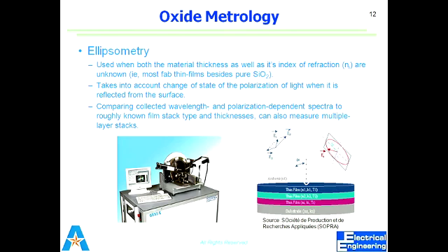Okay, so the incident angle that we are using is 70 degrees in the lab, and the light that strikes is laser light. The laser light strikes, and after that, due to the change of state of polarization, the detector detects it and the microprocessor inside the computer manipulates it, and you will get the thickness that is measured by the ellipsometer.